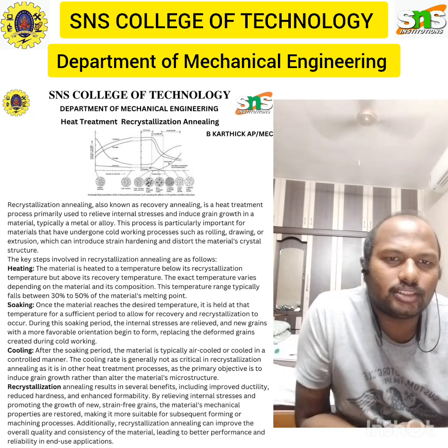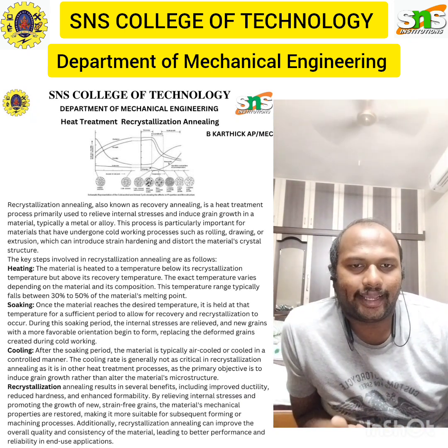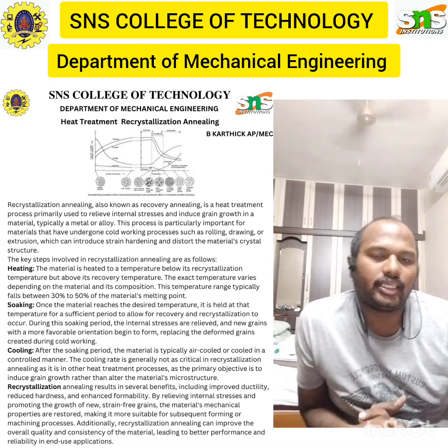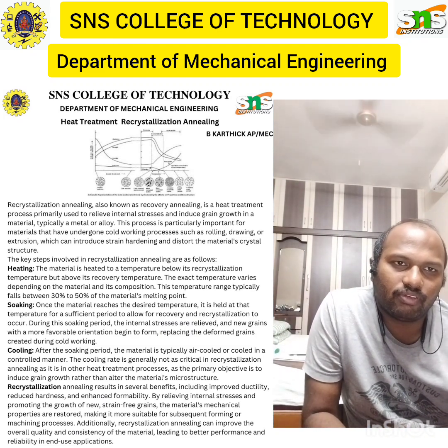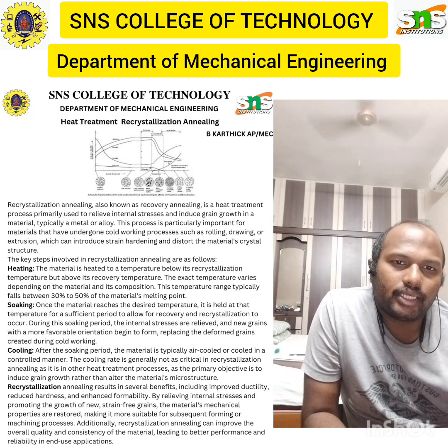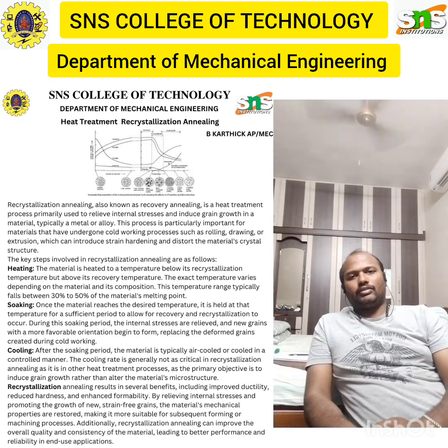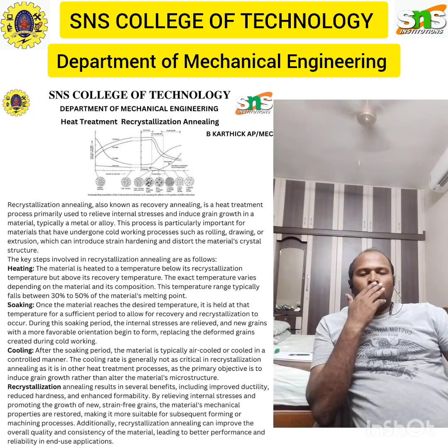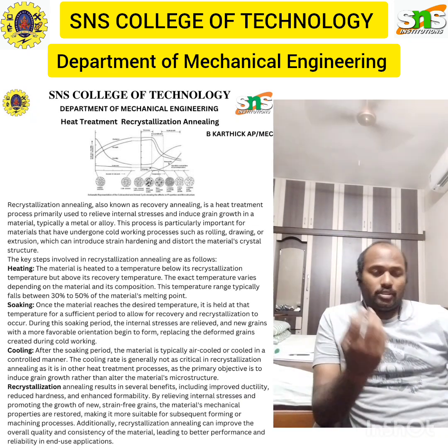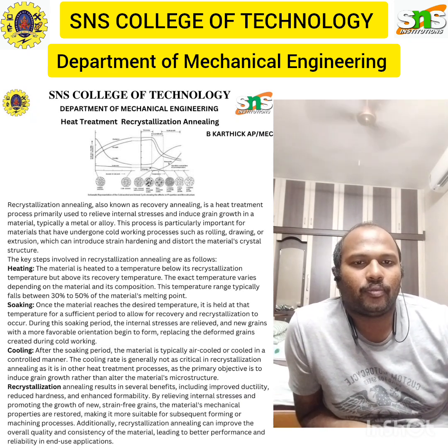As this spheroidizing is taken into consideration, we have an iron called spheroidizing iron, that is SG cast iron, which is used to make the brake drums for heavy vehicles. So here in spheroidizing, we are going to convert plate-like or thread-like carbides into bullseye, that is into spheroids, so that the hardness is slightly reduced.